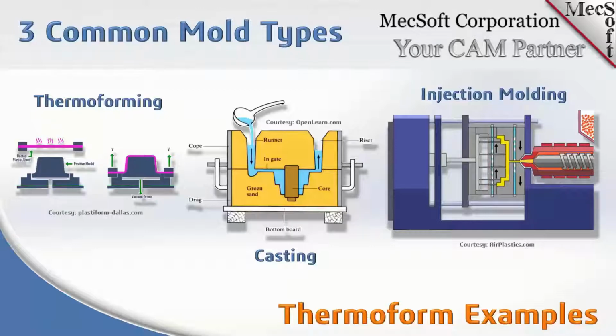So you've got to create that blank, machine that blank ahead of time, and then you use that to mold or to form each half of the mold. And the material is like a green sand that sticks together, and it creates a cavity from that blank.